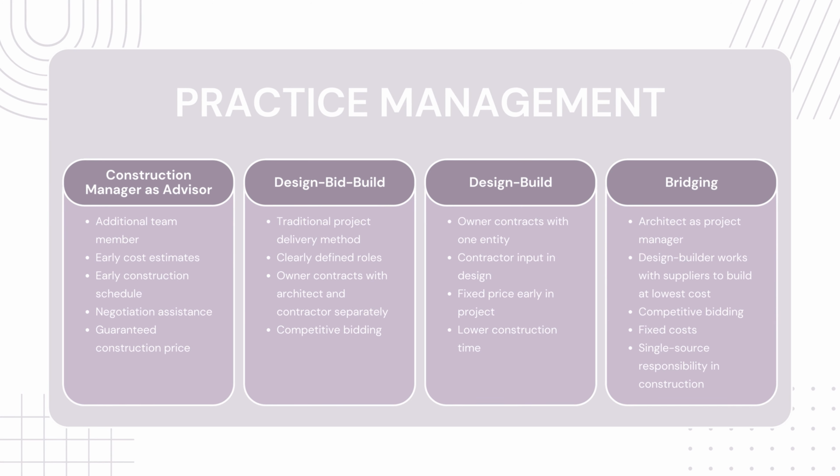Construction manager as advisor adds a third party to the project. They advise on constructability, provide early cost estimates, create the schedule, assist with negotiation, and provide a guaranteed price. Design bid build is the traditional project delivery method, and it's used a majority of the time. Roles are clearly defined. The owner has a contract with the architect and the contractor, and once the project is designed, it's competitively bid.